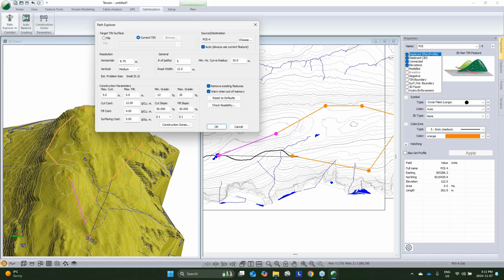So we'll typically see, in terms of things like radius constraints, smaller values in trails compared to roads. And we want to be cognizant of our whole project and how we're going to build this thing. So for this one, I'm going to go with a minimum radius of 10. So it's going to make sure we can get a little wagon around there with a trailer for actually constructing